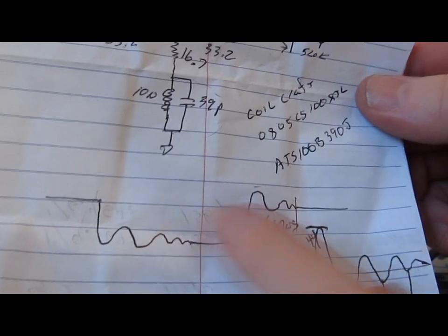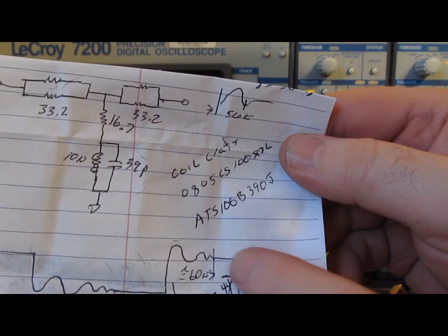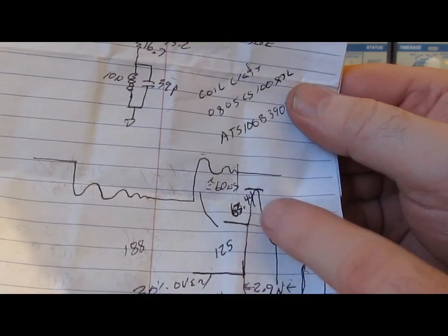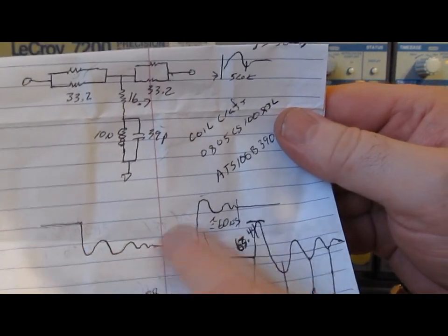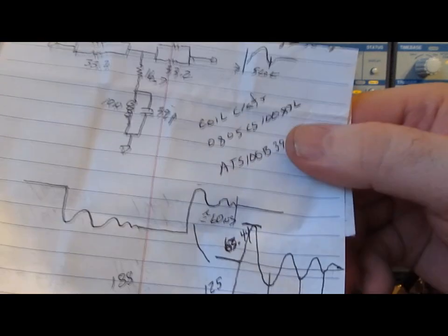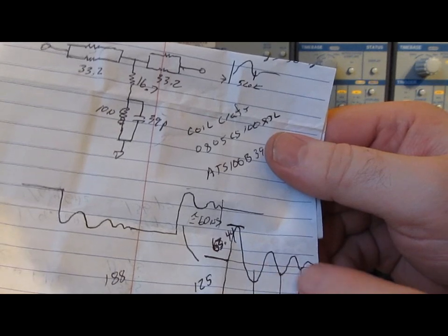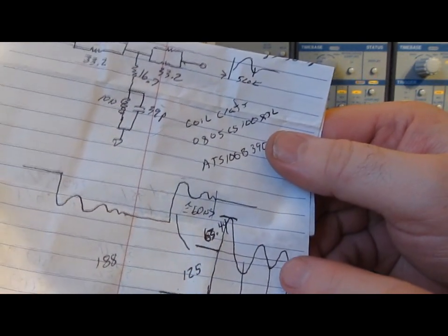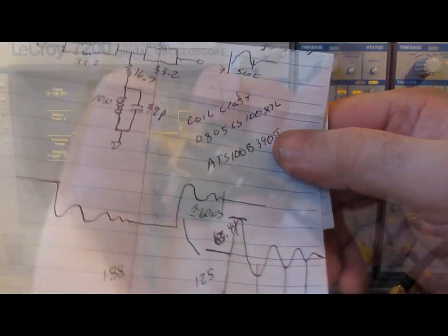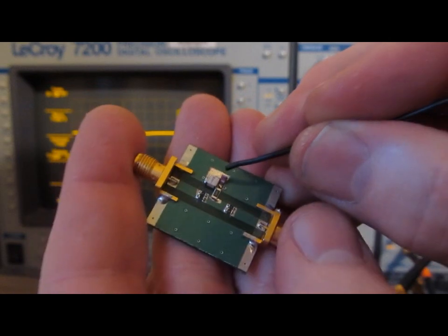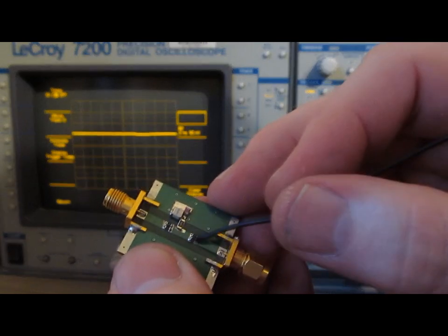So I had simulated this using MicroCap, where the other one was critically damped. This one we're going to actually generate some overshoot, hopefully. So the amount of overshoot is basically going to be 30% higher, and the same thing for the undershoot. And as this rings out, the very first dip should be roughly 2.9 nanoseconds out. The second dip is at 7 nanoseconds out. And the third dip is roughly 11 nanoseconds out. So right here is our inductor. Here's our capacitor. And then these 5 resistors here make up our splitter.